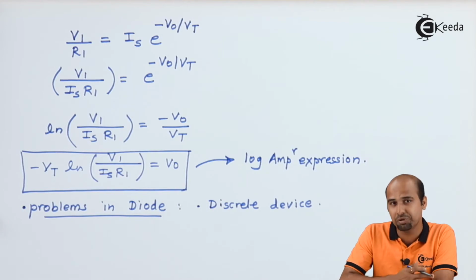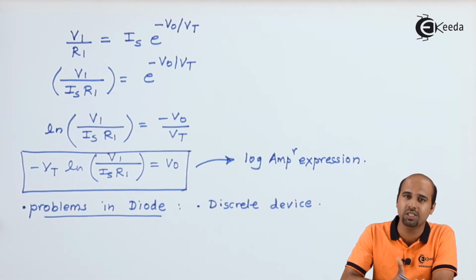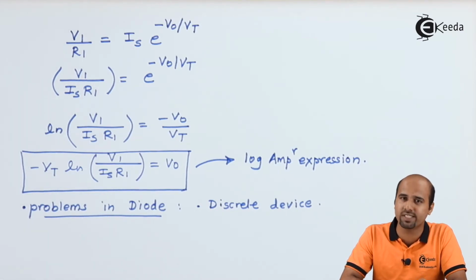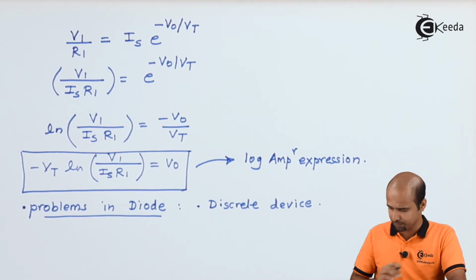So what we can do is form a circuit in such a way that I will replace the diode with a transistor by having one short circuit connection, such that this transistor will altogether act as a diode itself, and operation will act as only log amplification, right?